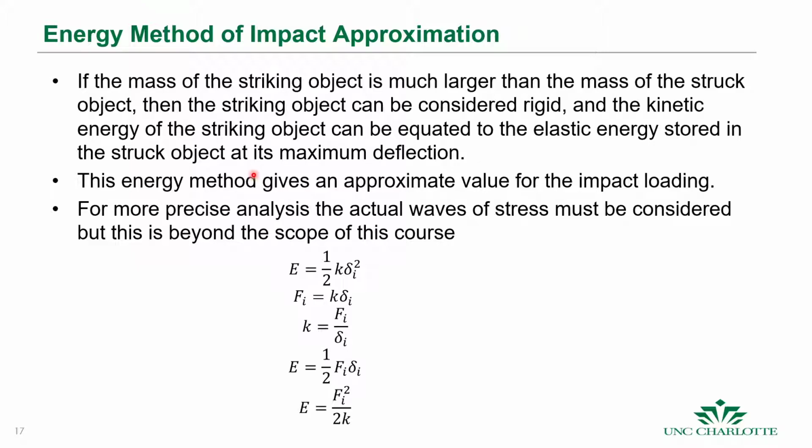The energy method gives us an approximate value for impact loading, but if we wanted to have a more precise analysis, we'd actually have to look at the waves of stress and analyze how they go through that material, but obviously it's beyond the scope of this course. You could take theory of elasticity and some advanced finite element analysis classes and start to look at the mechanics of these events in grad school or self-study later on. But for us, we can just look at the energy associated with impact.